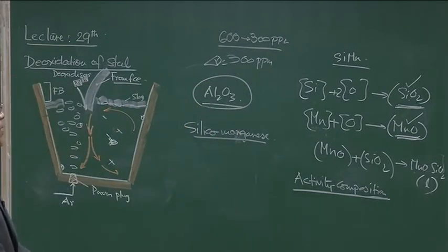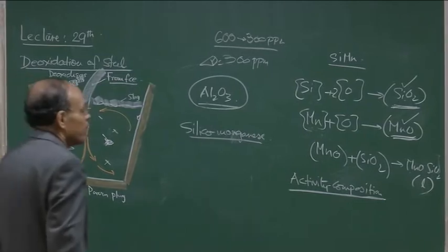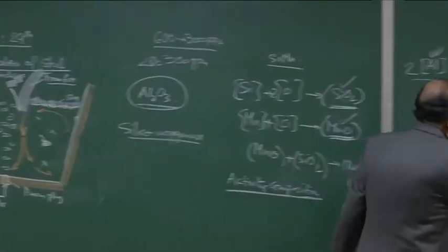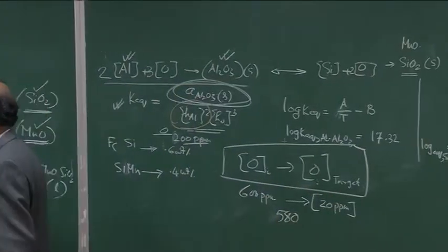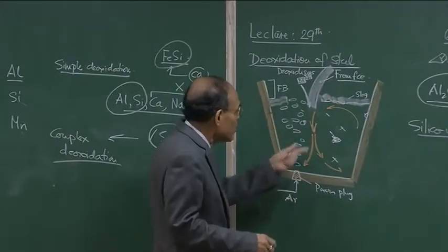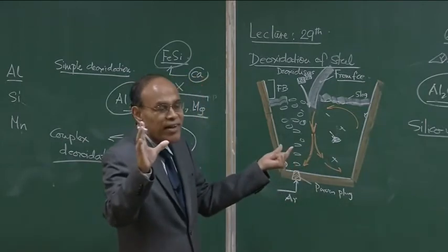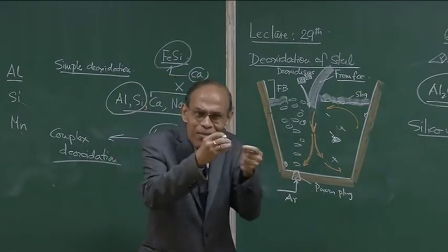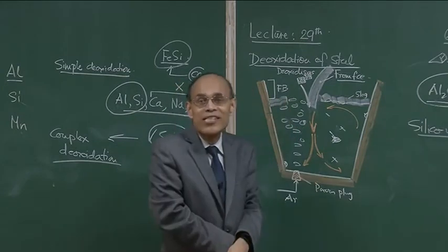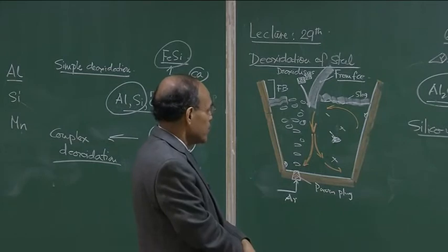necessary calculations pertaining to deoxidation of steel, and then you can determine, to satisfy a given oxygen target, how much deoxidizer you have to add into the bath. And as I said, if after doing the deoxidation there is some problem and you have not achieved the target deoxidation, then you can do a trim adjustment during subsequent stages, and that we will discuss when we talk about the ladle metallurgy steelmaking process.